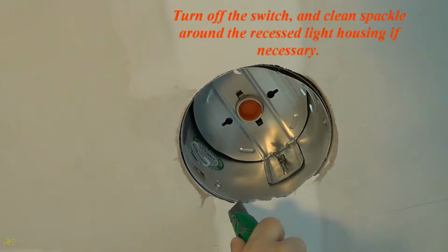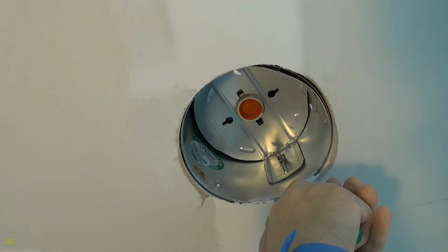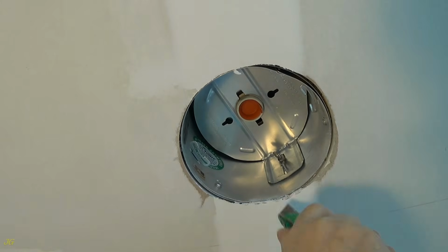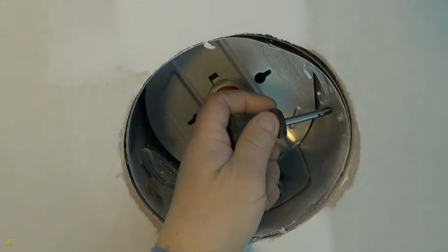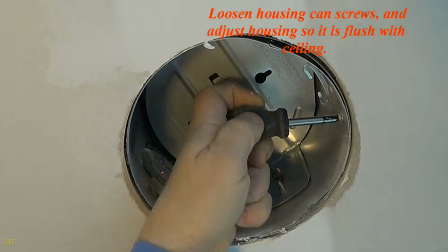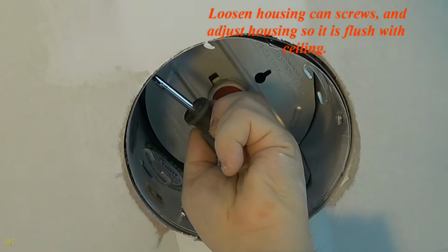Turn off the switch, and clean spackle around the recessed light housing if necessary. Loosen the housing can screws and adjust the housing so it is flush with the ceiling.